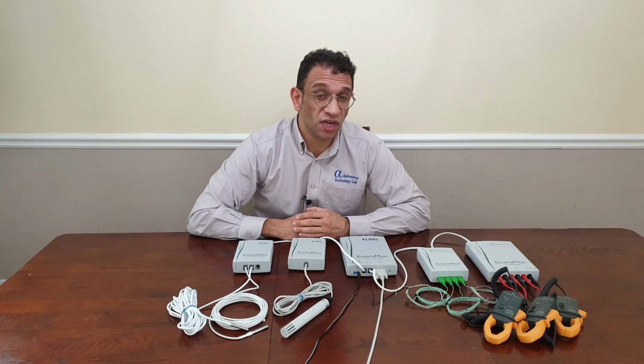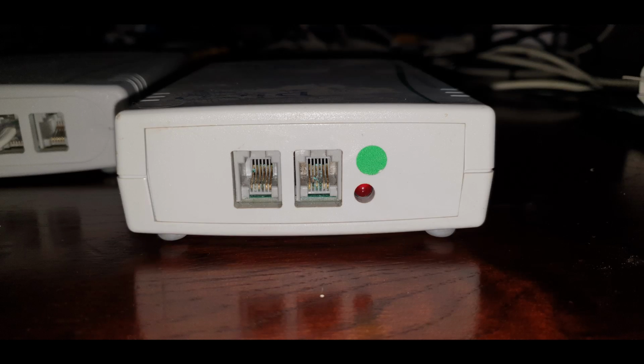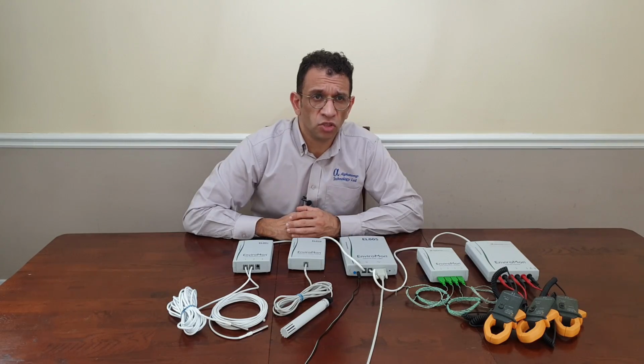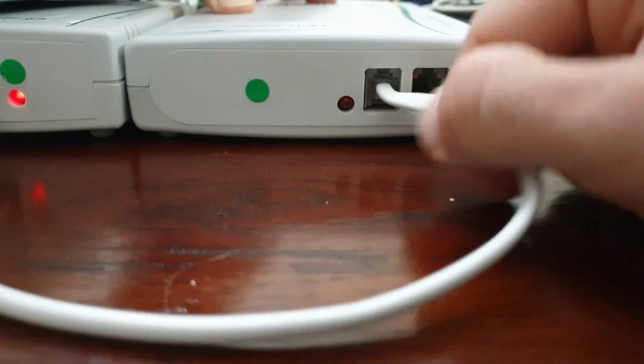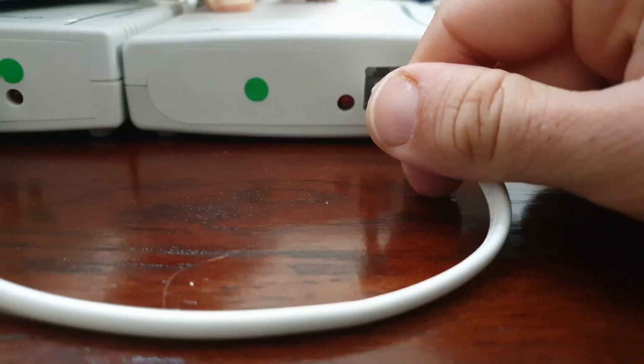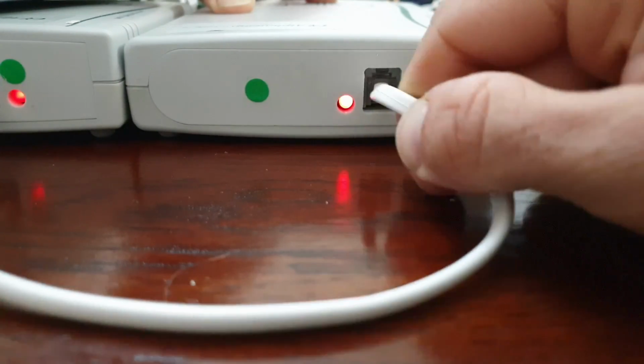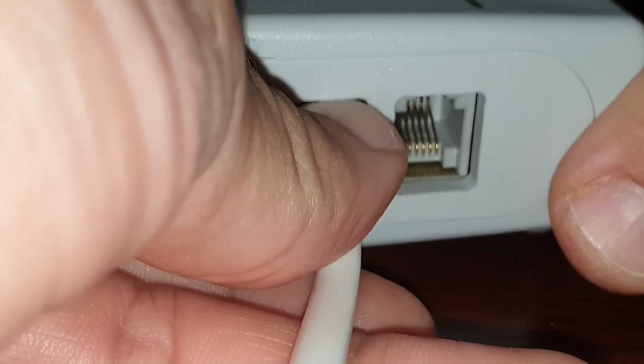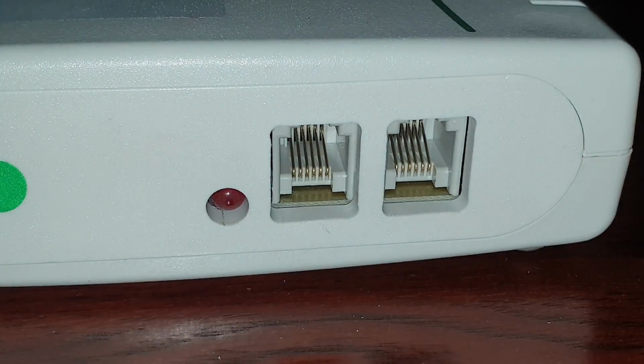The EnviroMon system is quite a robust system and can last for many years. In fact, we have some systems that have been out there for over 15 years. Now over the years, some of the issues that we've seen have come from the ports on the data logger, converter and alarm units, where they've come off the PCB, or the pins have been bent, or there's been corrosion due to water damage. So the network ports should be fairly secure when you lightly wiggle the converter cable, as you can see here. You can take the converter cable out and have a look at the port and see if there's any signs of corrosion or if the pins have been bent.